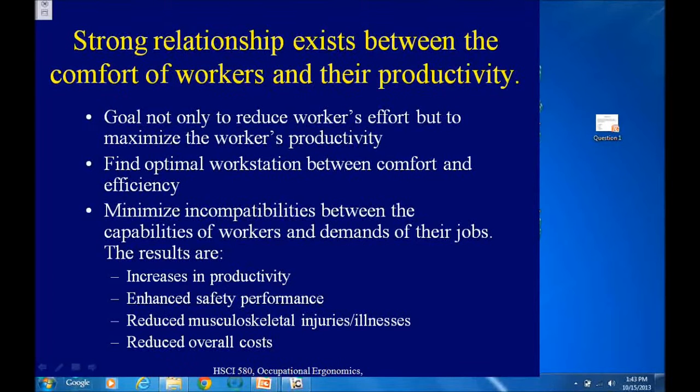So keep that in mind, that you wouldn't be designing for a range now in workstation design. You're designing to accommodate a certain percentage of that population. So, for example, if you designed for a clearance aspect of a workstation design, you'd be designing for the taller end, meaning that all the other people who were shorter than that particular stature would be able to be accommodated because of their smaller size.